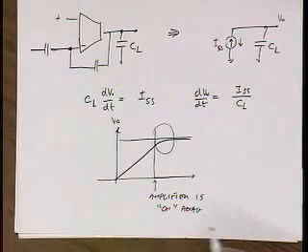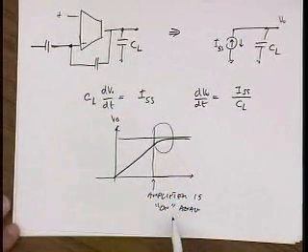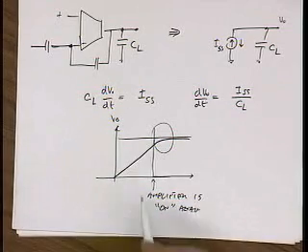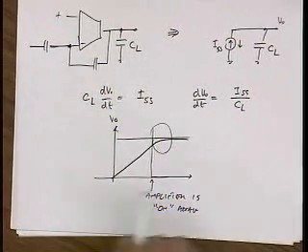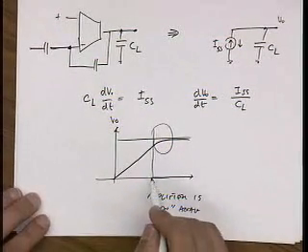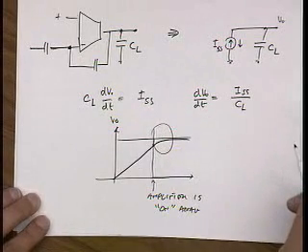And of course, because we don't like dealing with nonlinear differential equations, we make it piecewise linear. So we assume that the amplifier is off and then all of a sudden it's on. There's going to be some smooth transition between on and off, but for simplicity we can just assume that if we've waited long enough, then after that wait, my amplifier turns on and I get linear settling.